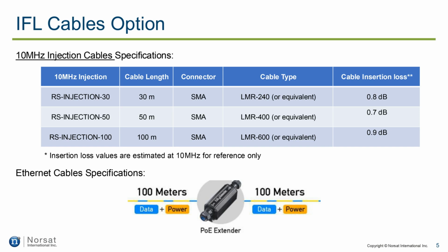Speaking of Ethernet cable specifications, we need to be aware of the distance between equipment. Power over Ethernet (PoE) provides a convenient and cost-effective approach to achieve both power and data connectivity on a single connection. However, since it is an Ethernet channel, it's highly restricted by the 100-meter distance limit. Cable length is limited to 100 meters due to Ethernet signal restriction unless extra accessories such as a PoE extender are used to amplify the signal to compensate for the cable loss.